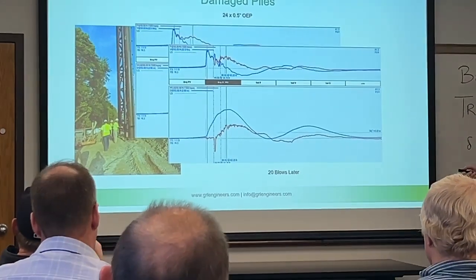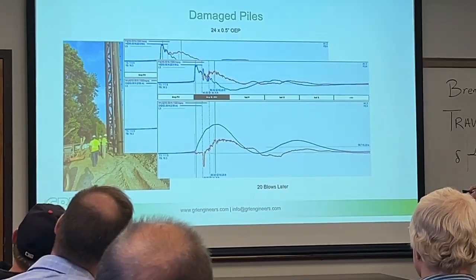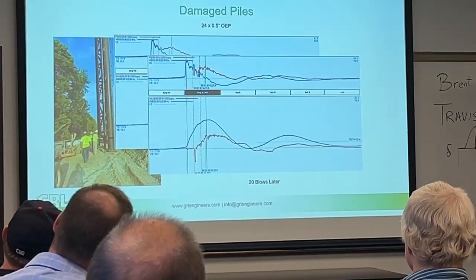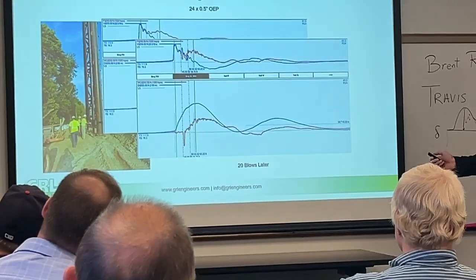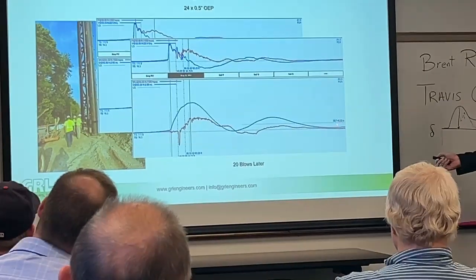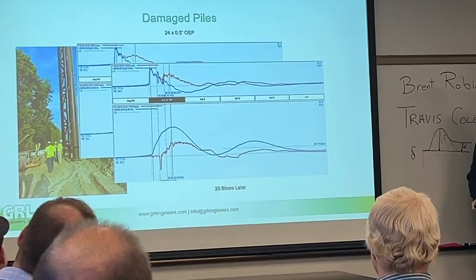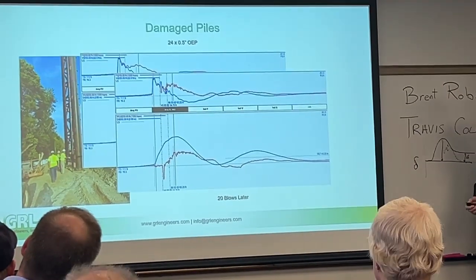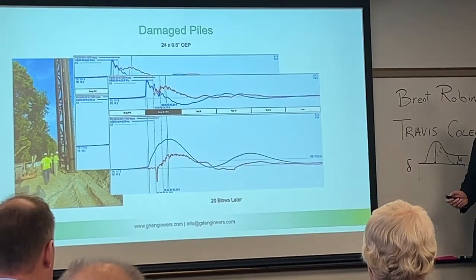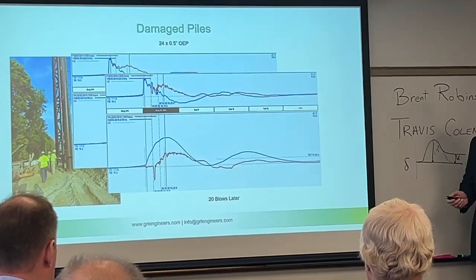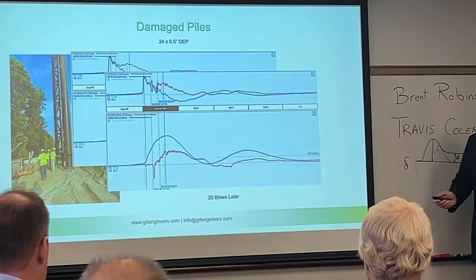We drive a little deeper, and now we see a big opening, or a big break in our impedance. And this was really concerning because we are only at 4 blows to the inch. So this wasn't hard driving. No, we hadn't gone through hard driving. There's no reason to have this splice break. It didn't have any excessive stresses delivered to it. There's another blow where it comes apart even further.